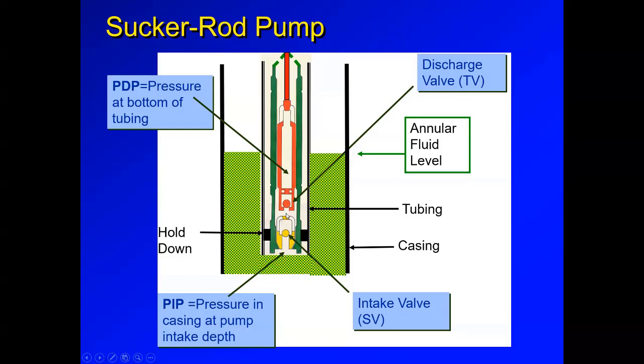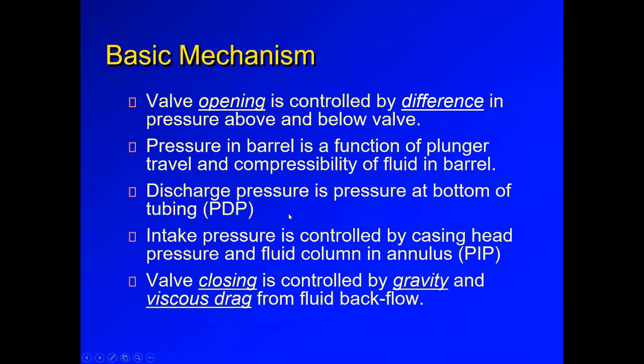What is going to be changing a lot is the pressure inside the chamber, as we compress the fluids above the discharge pressure and, in another portion of the stroke, allow the standing valve to open and fill up with liquids from the well. We'll be talking about how that pressure fluctuation dictates the card shape. So basically, that is the pump mechanism.